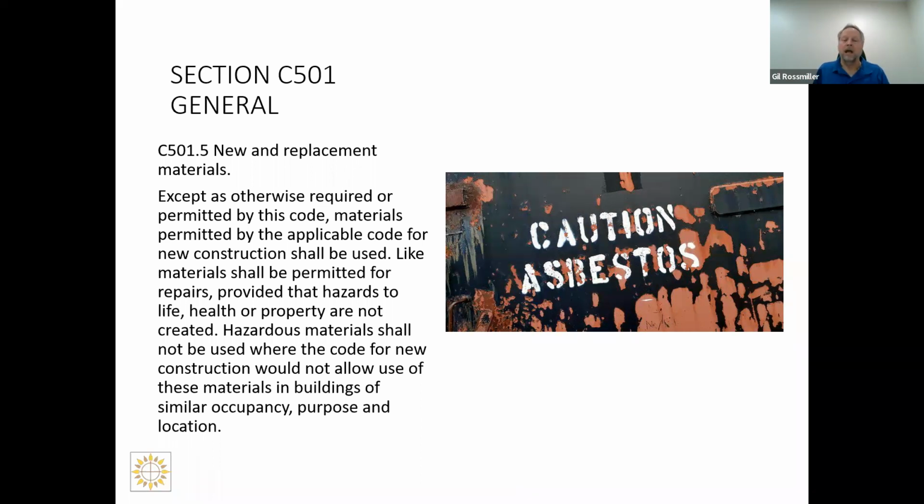Now it's part of my thermal envelope. I take the sheetrock off and there's no insulation at all. Now we have an opportunity that really isn't going to set anybody back, by putting in some R13 batts or something in that cavity. It's just going to make it perform better anyway. Good question.